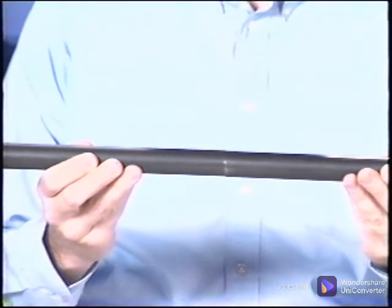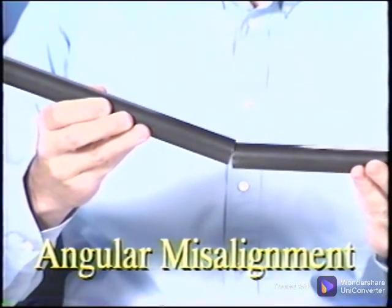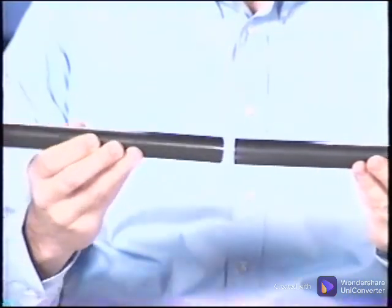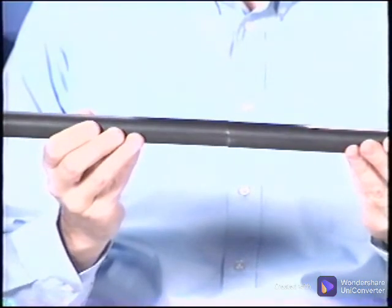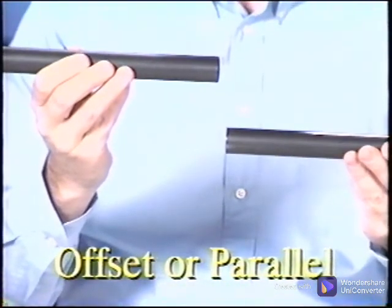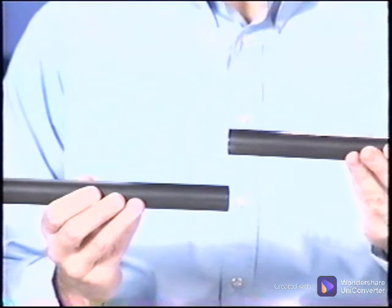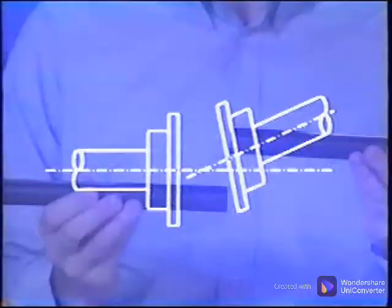One common type of misalignment is angular misalignment. The two shaft center lines meet, but they meet at an angle. The shafts could be at an angle horizontally or vertically, but it's typically a combination of the two. The second type of misalignment is offset or parallel misalignment. The shafts are parallel, but the center lines of the shaft don't match up. In fact, the shaft center lines never cross as they do in angular misalignment.